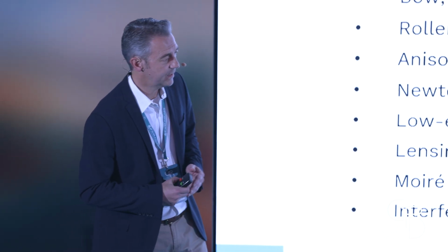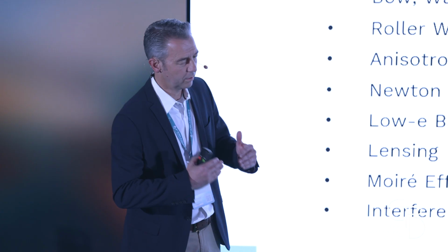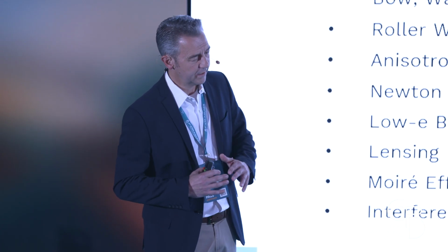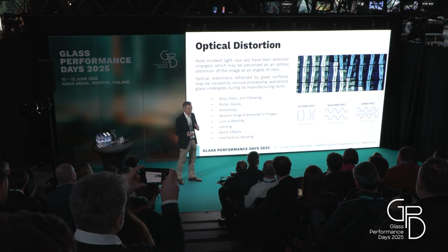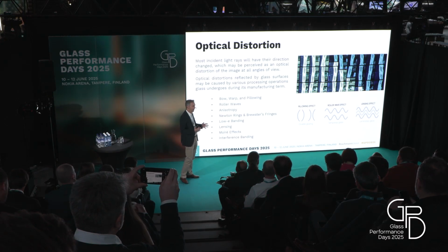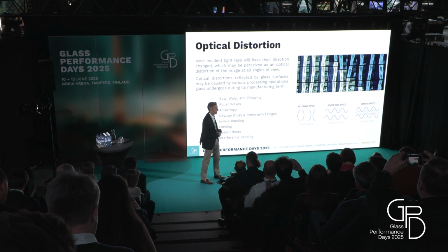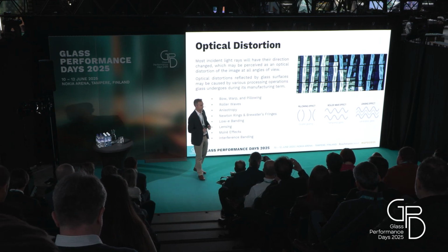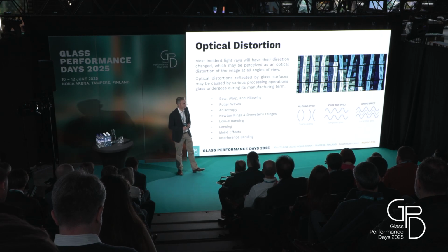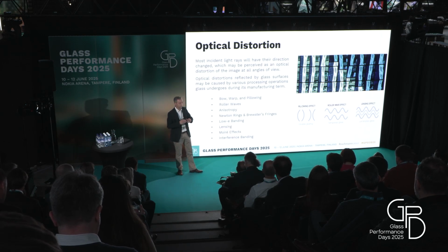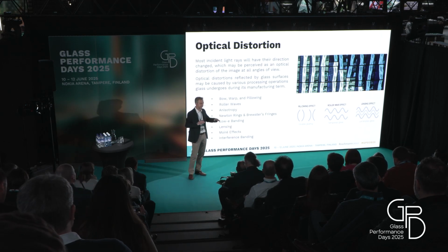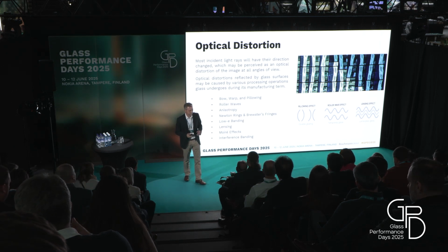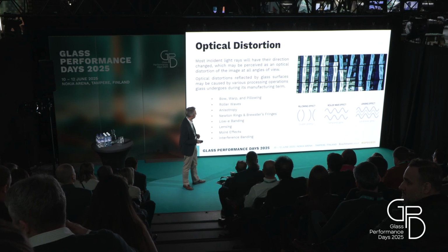All we see is basically where the surface of the glass is either bent or distorted by, for example, a roller wave, and marrying two roller wave surfaces then creates a kind of lensing effect where, in laminated glass, we are bonding two glass surfaces together, and the irregularity of the surface of these different roller waves then creates that kind of distortion.